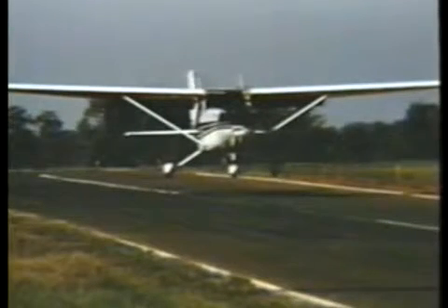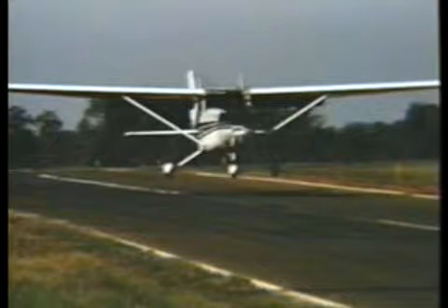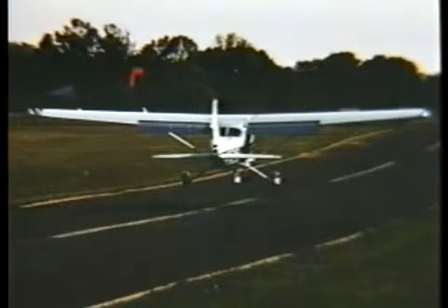Now, how many of you are aware that landing at less than the maximum landing weight can also result in your landing long? Well, it can. And it will. As you'll recall, a little earlier in this program, we said that if you don't have a published approach speed, you should carry 1.3 VSO on short final.